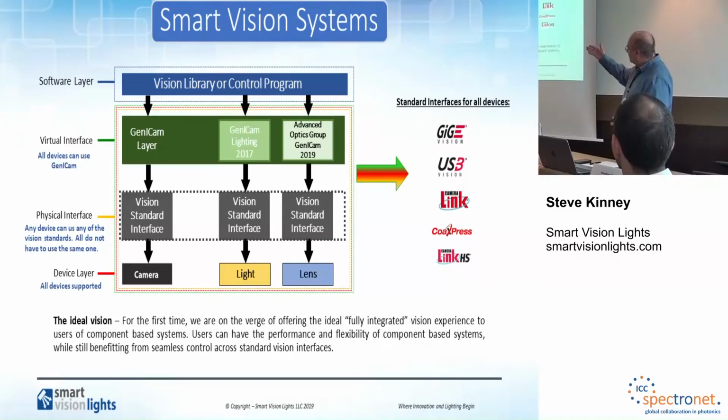Once we have it on GenICam, then as I was alluding to earlier, all the software functionality is available on any of these physical layers, because all these standards through the AIA or EMVA and JIA are supported by GenICam as the link to the host software. So GenICam itself is virtual and has no physical interface, but all the things you would recognize as a physical interface for cameras and for vision, in fact, are running GenICam behind them.